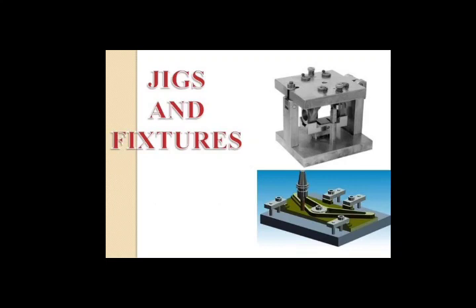Next was nesting. A nest is used for workpieces which do not have machined edges or holes to locate. Machining methods are generally used for symmetrical workpieces and casting methods are used for unsymmetrical workpieces. In the case of short-run production, a nest can also be made from plastic or epoxy resins.